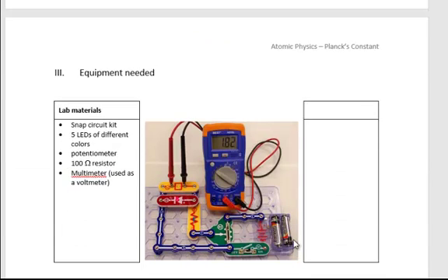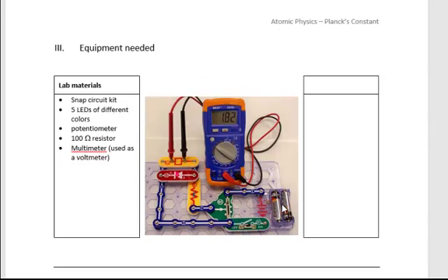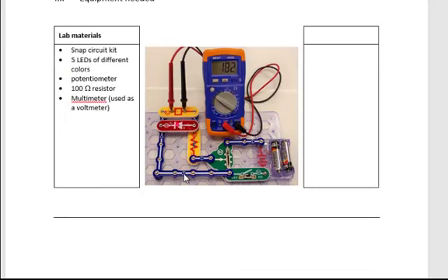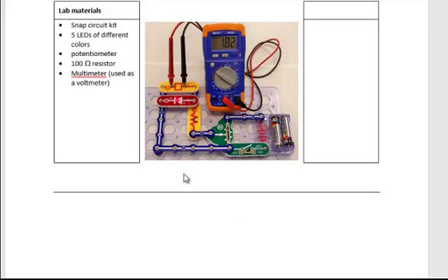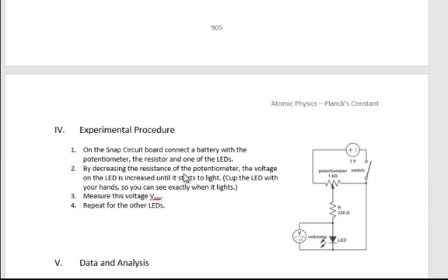Now the LED experiment actually will do that, and this is the setup that I used. I used almost the exact same setup as you see here, and then interestingly I made a mistake at first. I'm trying to figure out this is actually where the LED is that should be measured eventually, and I put that LED in just for checking. Turns out it's actually in the way, even though it's parallel to the other one. It actually took voltage away from the other one. I have to figure out why that is. In any case, I took it out and was able to proceed, and you will see how that worked out.